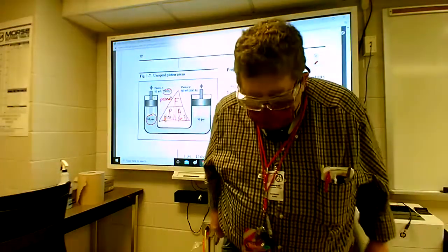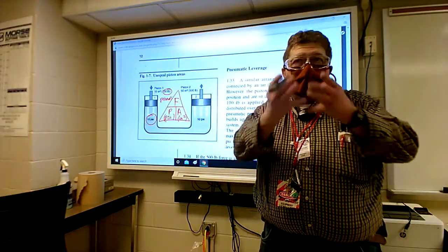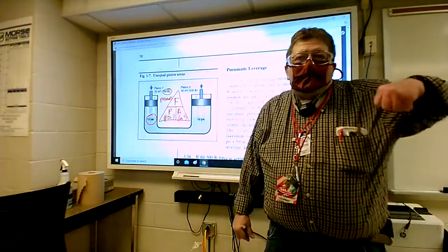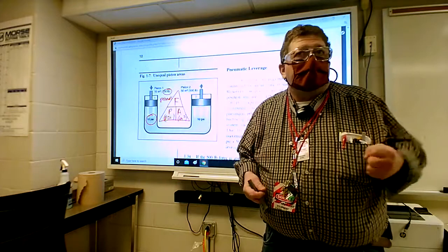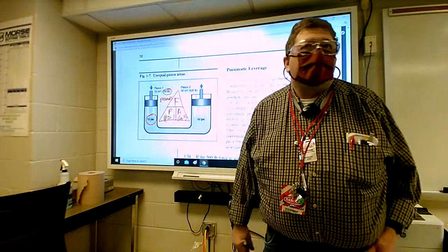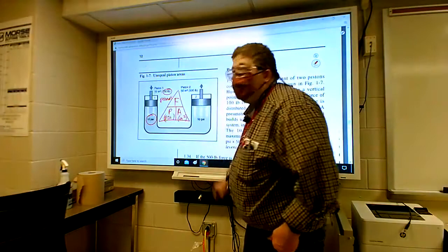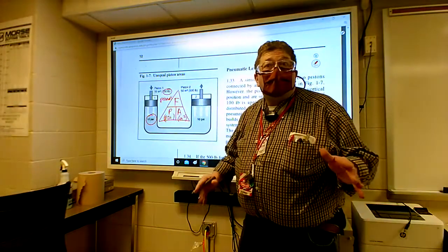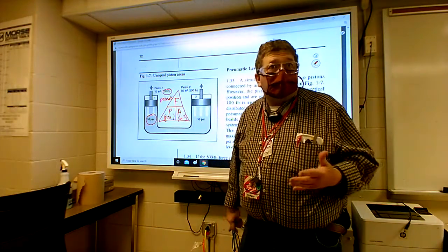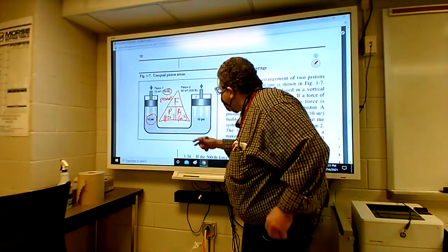Right. So if you've got a vessel, it doesn't matter what the vessel's shaped like. It can be oblong, it can be like a U shape. If it's enclosed and there's no leaks in there, and you pressurize it, it'll be equal force in all directions within that vessel. So it says that if it's 10 PSI over here, then it will be over there too. That is if the fluid is actually under static pressure. If it's not leaking, if it's not moving, if it's not escaping out of there.